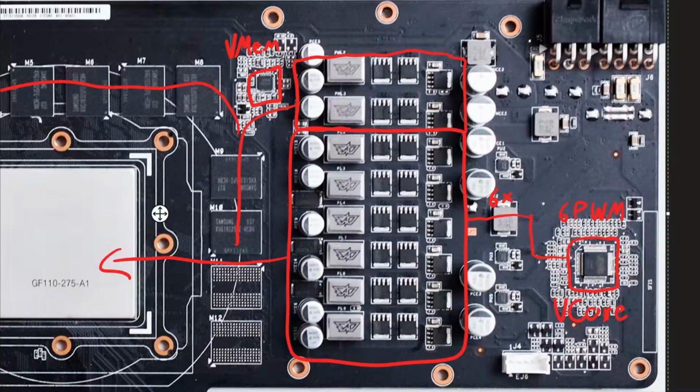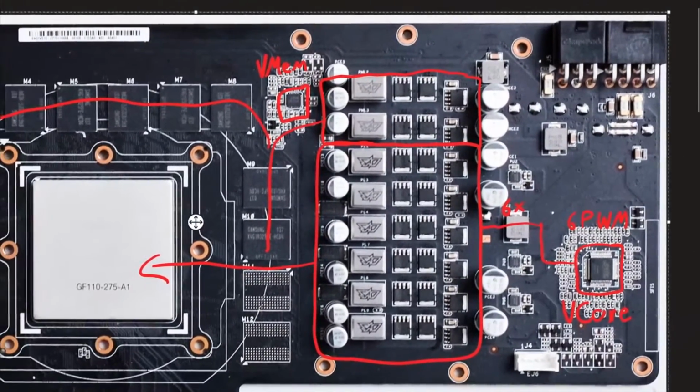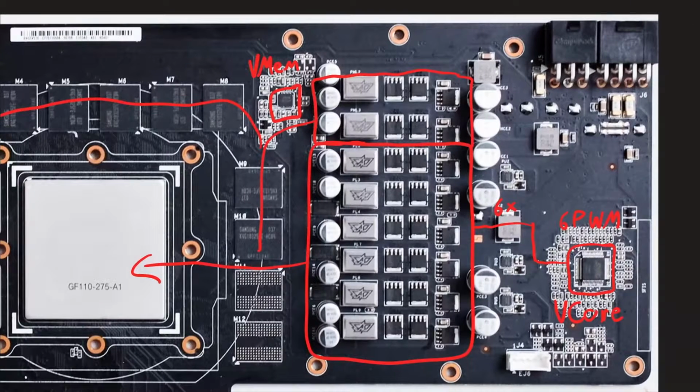Motherboards usually have only one PWM controller. Sometimes you can find an 8-phase PWM controller where 6 of those phases go to vCore, and then 2 to SoC, which powers iGPUs, and on Ryzen it powers the memory controller, I think.